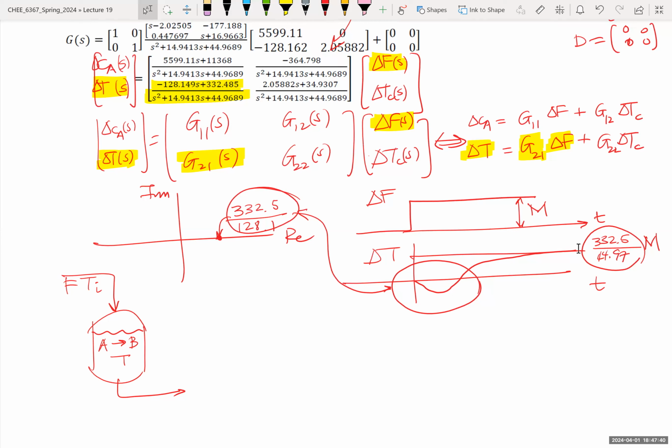So the zeros of the individual transfer functions say something about the individual effect of each input variable on the output variables. The poles of the system tell us what happens with regard to stability of the system. So is this system stable around that steady state? Yes, because all four denominators have roots in the left half plane, correct? Why do they have roots in the left half plane?